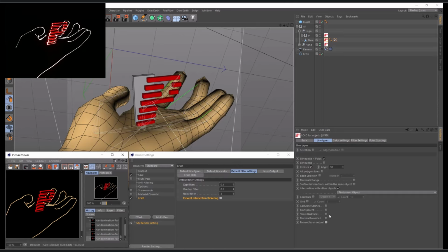So undo this one, render it again. And the better option would be to use the render option of only rendering a silhouette. Instead of silhouette and folds and creases, we deactivate this one and I just activate only silhouette. And if I render this one, you will see we're reducing not 200 points, but in this case, we can anyhow reduce the overall points to 1610 points. So also quite significant reduction of points.